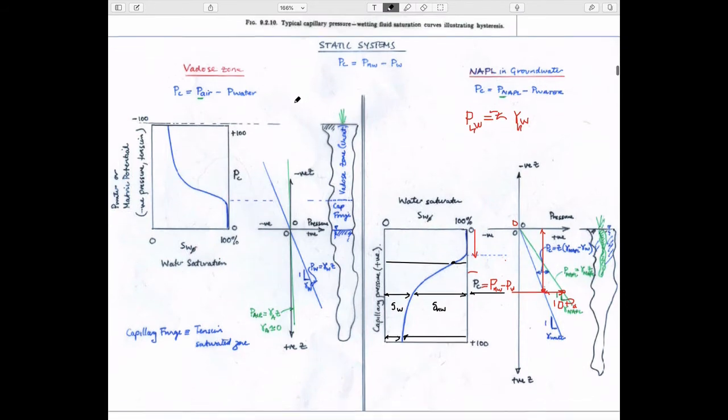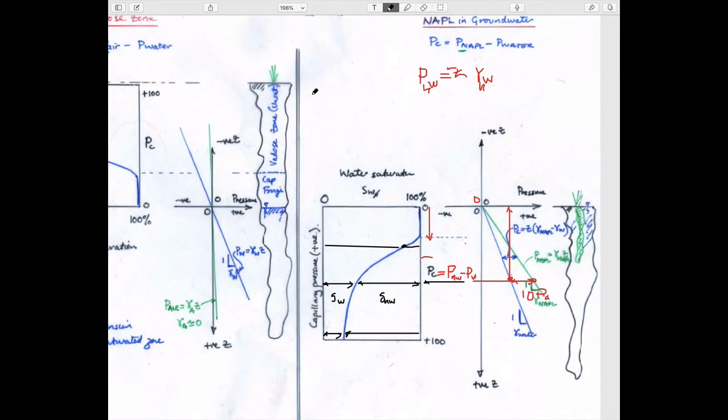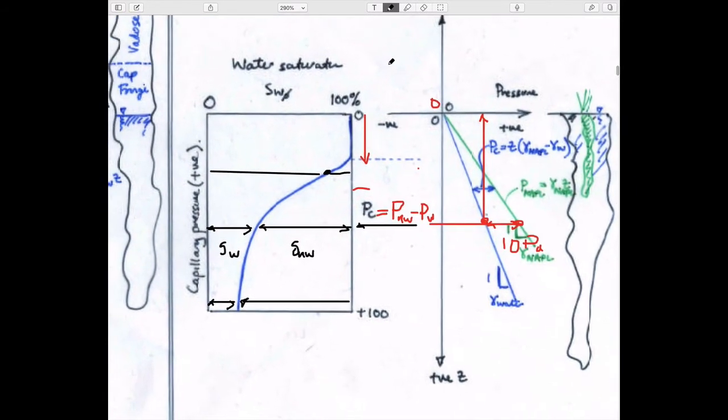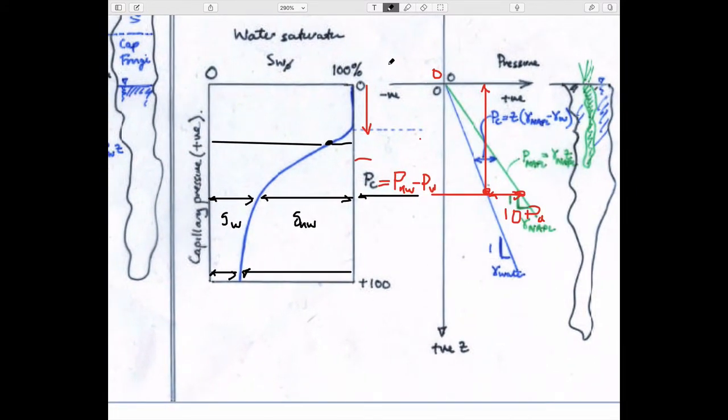So, straightforward, I think, right? So in this particular case, we've worked below the groundwater table and we've defined that. So it says what the distribution is. So that's for the case where we have water that's being invaded by a denser than water oil. What happens if it's a lighter than water oil in the system?